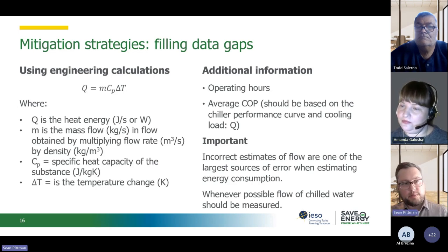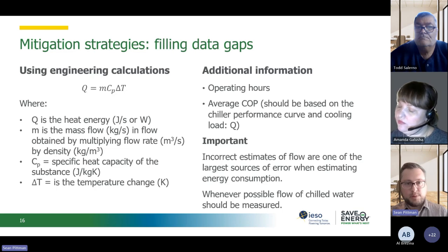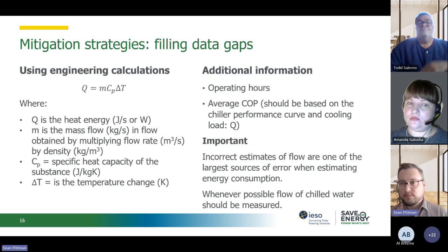Yeah, it does definitely depend on your project and what you're doing specifically, but usually, obviously, with chillers being the largest piece, understanding how much energy that chiller is consuming is probably the biggest piece of information you can get. And then second to them is chilled water flow rate or temperatures, trending temperatures between chilled water supply and return over time. So that you can estimate the efficiency of those chillers and understand what that chilled water flow rate or chilled water loop is doing.